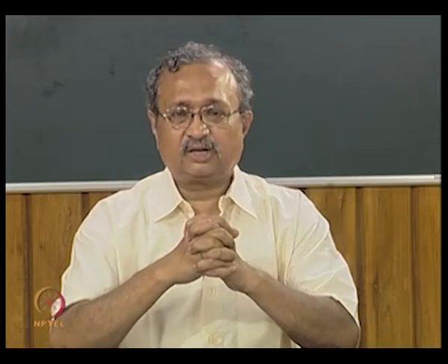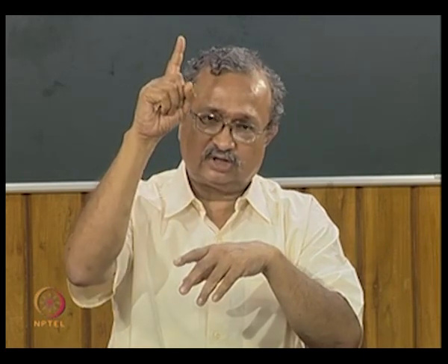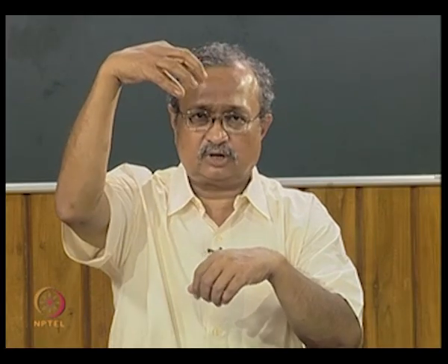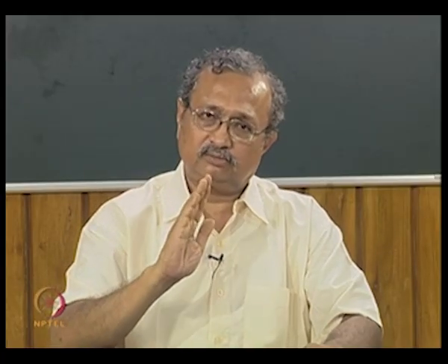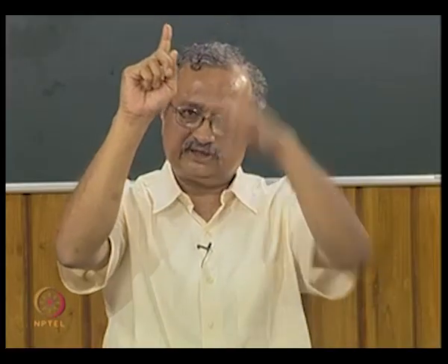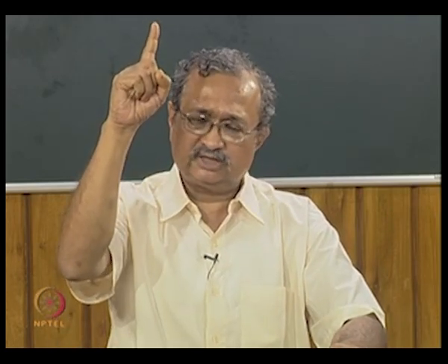Like, if we do not want anyone to touch some overhead hanging object, we should consider the maximum arm reach, that is the 100th percentile length, so that below that height, all the people will not touch that dangerously hanging thing.